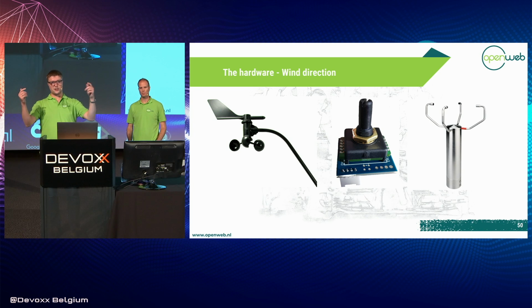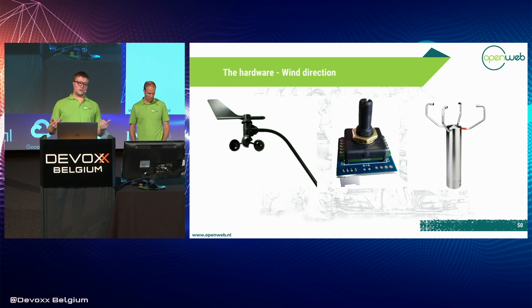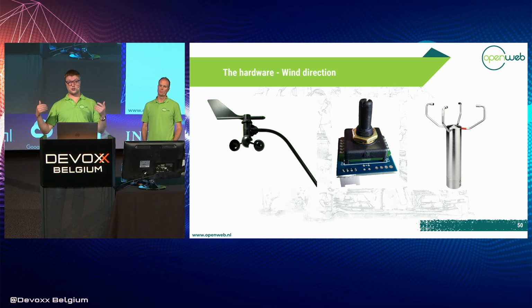So there are 4 ultrasonic microphones you can compare them to, and by the flow of the wind, one or 2 microphones will produce static noise, and the louder the noise is, the more wind there is. From the microphone that picks it up, you know the wind is coming from the opposite direction.